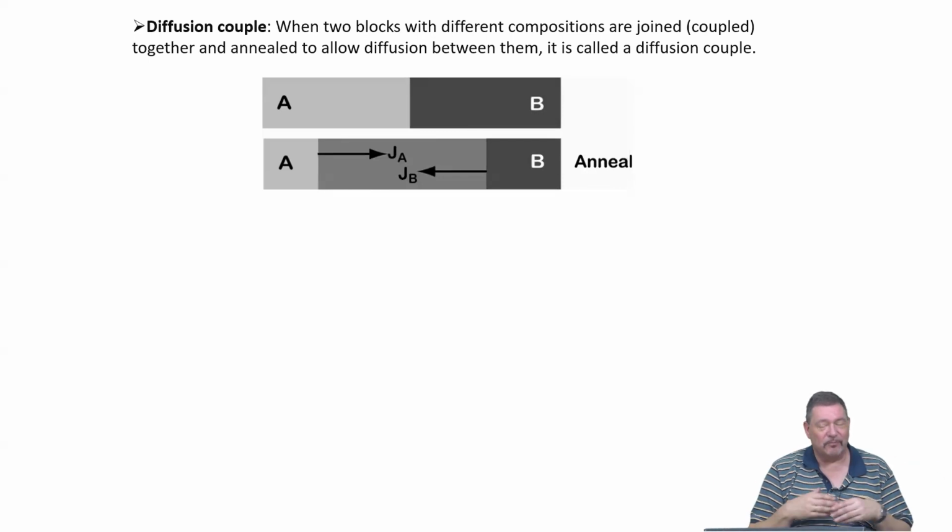Because it's an Arrhenius type process, meaning it gets much faster if you increase the temperature by a reasonable fraction. You could also wait longer at the same temperature, right? So diffusion experiments are nice because you can independently control the temperature at which the diffusion process takes place, and you can vary the time which you give the diffusion process to occur.